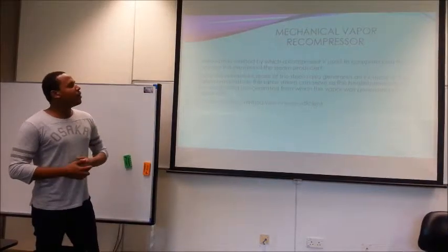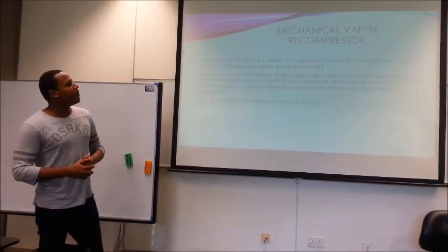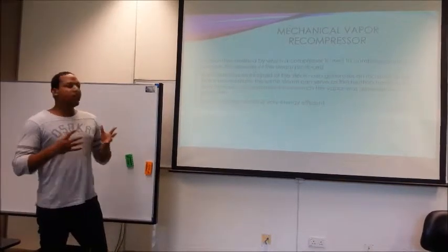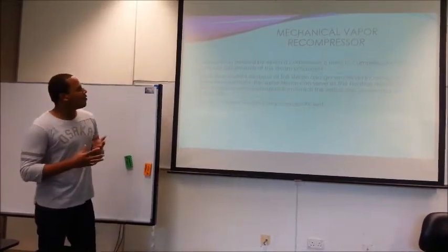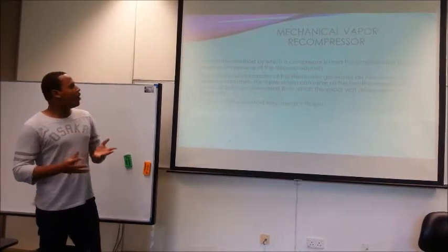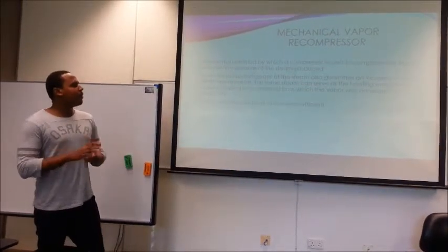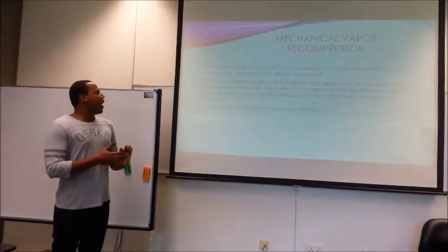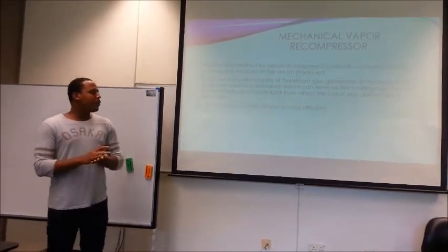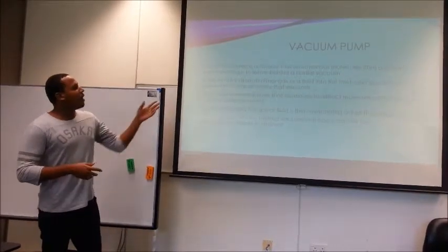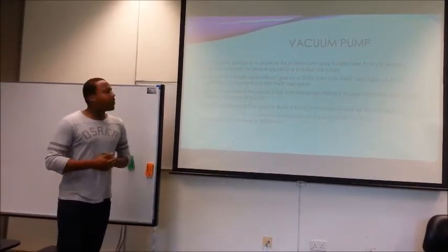So the mechanical vapor recompressor: since the pressure increase of the steam also generates an increase in the steam temperature, the same steam can serve as the heating medium for the liquid being concentrated, and this evaporation method is very energy efficient. Then we go to the vacuum pump.